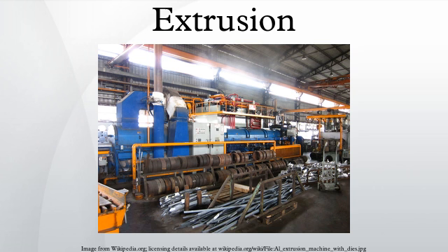The extrusion ratio is defined as the starting cross-sectional area divided by the cross-sectional area of the final extrusion. One of the main advantages of the extrusion process is that this ratio can be very large while still producing quality parts. Hot extrusion is a hot working process, which means it is done above the material's recrystallization temperature to keep the material from work hardening and to make it easier to push the material through the die.